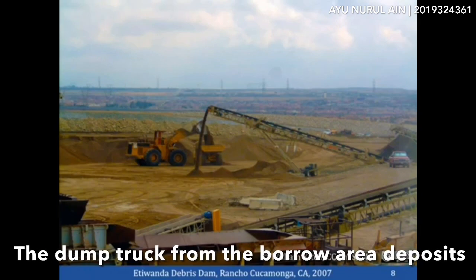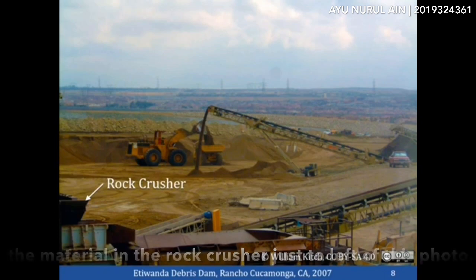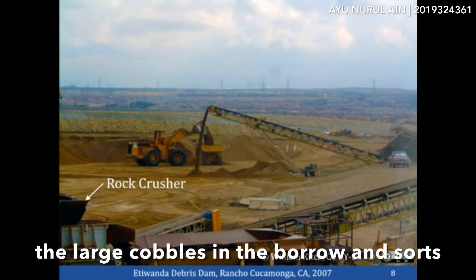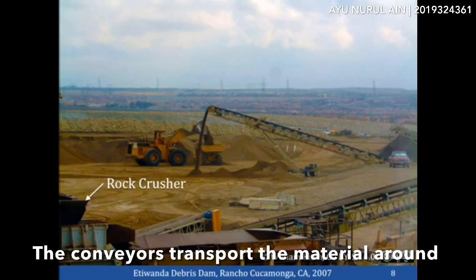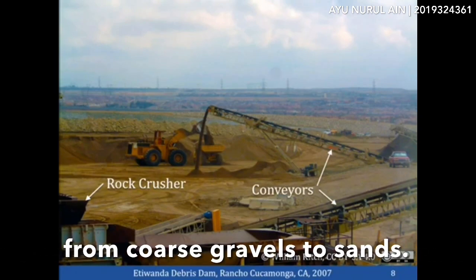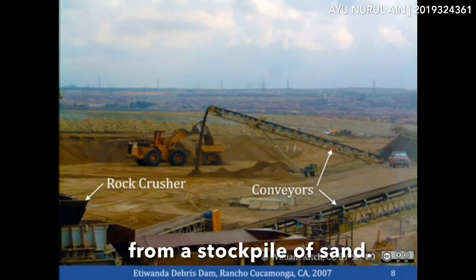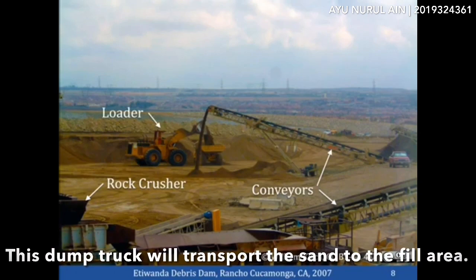The dump truck from the borrow area deposits the material in the rock crusher just to the left of this photo. This piece of machinery both crushes the large cobbles in the borrow and sorts the material into different sizes. The conveyor transports the material sorted by size into various stockpiles of different size material from coarse gravel to sand. In the background, you can see a loader filling up a dump truck from a stockpile of sand. This dump truck will transport the sand to the fill area.